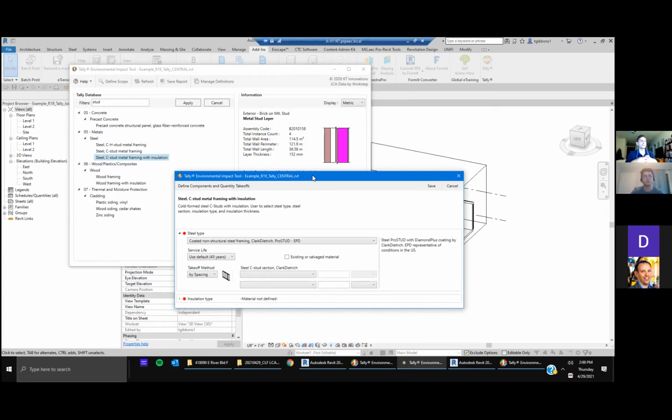You don't want to confuse Tally by thinking that it's solid, and I don't want to get into volume percentages of what the volume of the wall is or stuff like that. And again, Tally has made improvements over the time since I've been using it, so maybe it knows how to do all that. But because I desire full control at all times, I like to define exactly what the walls are. So it's a 6-inch stud, a 20 gauge. We'll say it's one way with perimeter, and we'll say it's 16 inches on center.